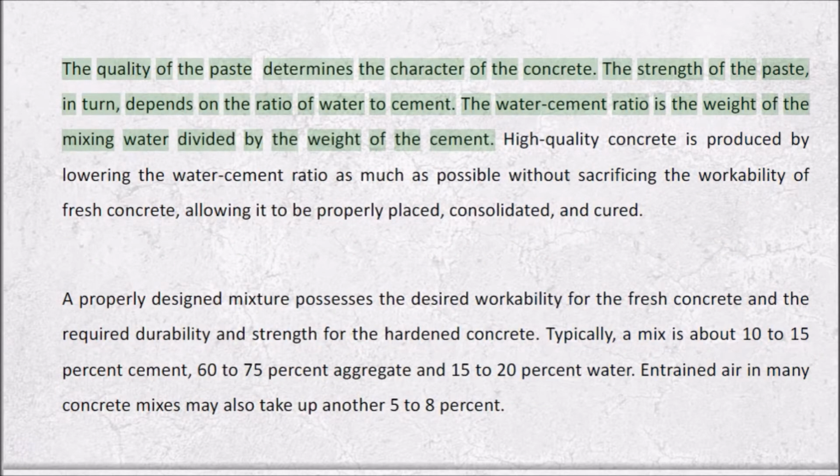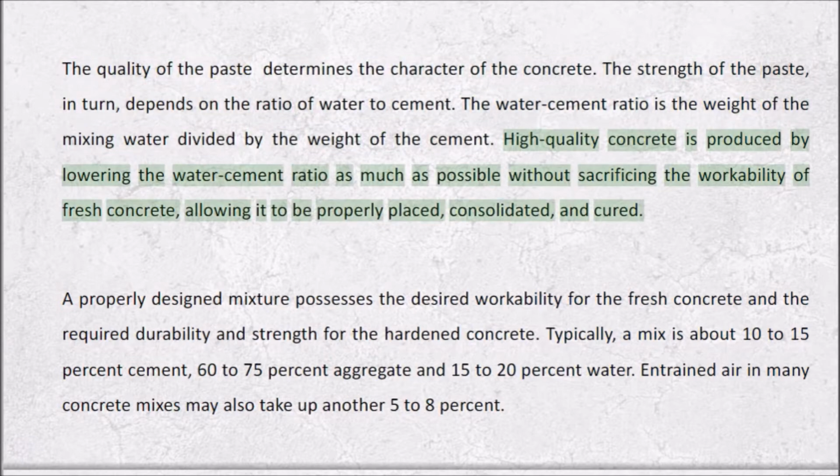The quality of the paste determines the character of the concrete. The strength of the paste, in turn, depends on the ratio of water to cement. The water-cement ratio is the weight of the mixing water divided by the weight of the cement. High-quality concrete is produced by lowering the water-cement ratio as much as possible without sacrificing the workability of fresh concrete, allowing it to be properly placed, consolidated, and cured.